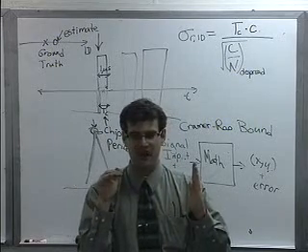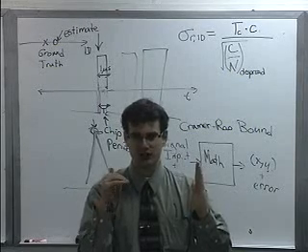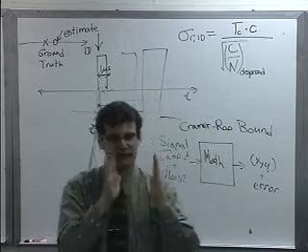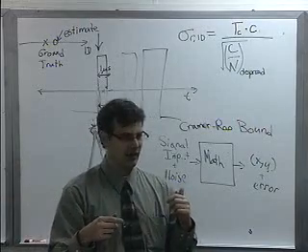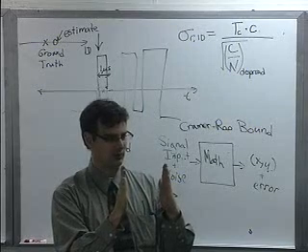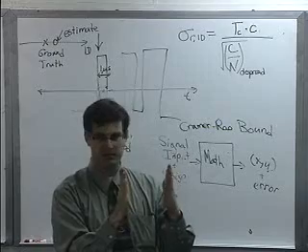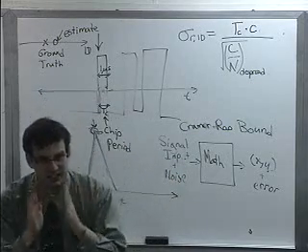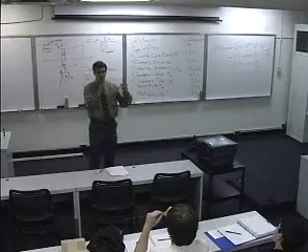And one of those 0.02 second bits that get sent will actually have 10 of those repeated. So GPS is one of a few signals where the frame length, the repetition length of your spread spectrum code, is different than a bit period. There are actually 10 frames of the same PN sequence, the same spread spectrum code, within one bit frame.